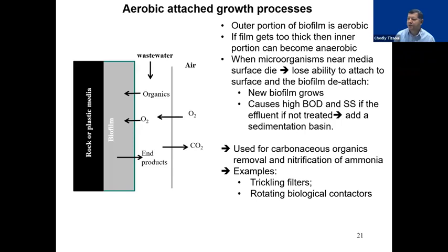I talked about this before when I introduced the problem, but just to emphasize the point about the attached growth process. You have a media, for example a rock or plastic media, where you have the biofilm, and then you have the wastewater phase there, and you have air. So from a mass transfer point of view, this is a very interesting problem. It involves a flow of wastewater, and you have the transfer of oxygen from the surrounding air to the wastewater, and then from the wastewater, the oxygen is transferred to the biofilm.